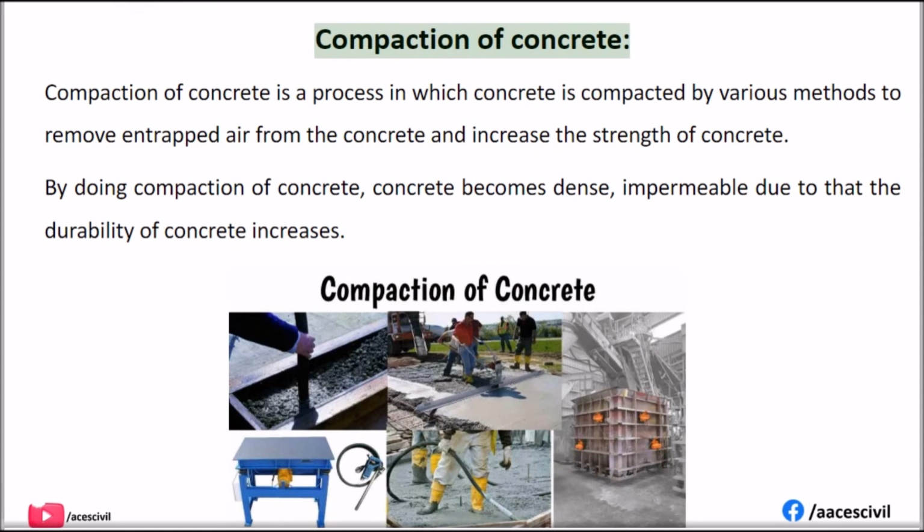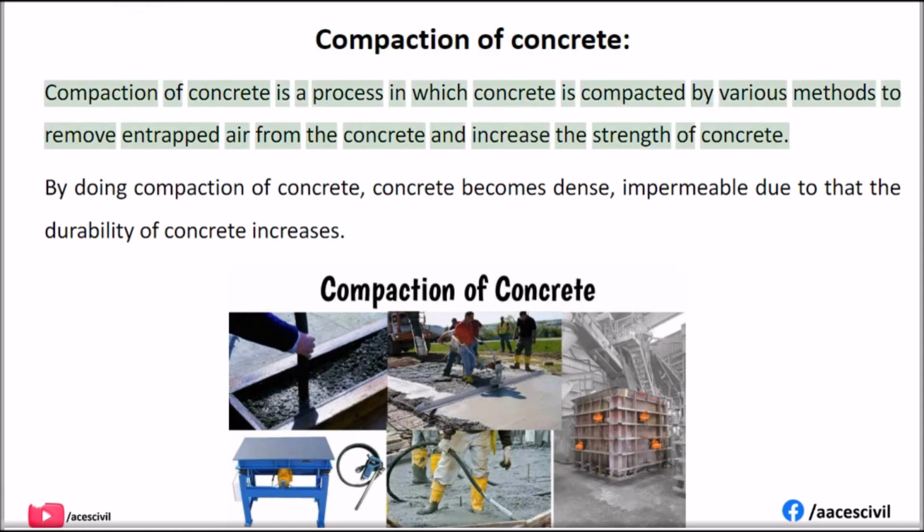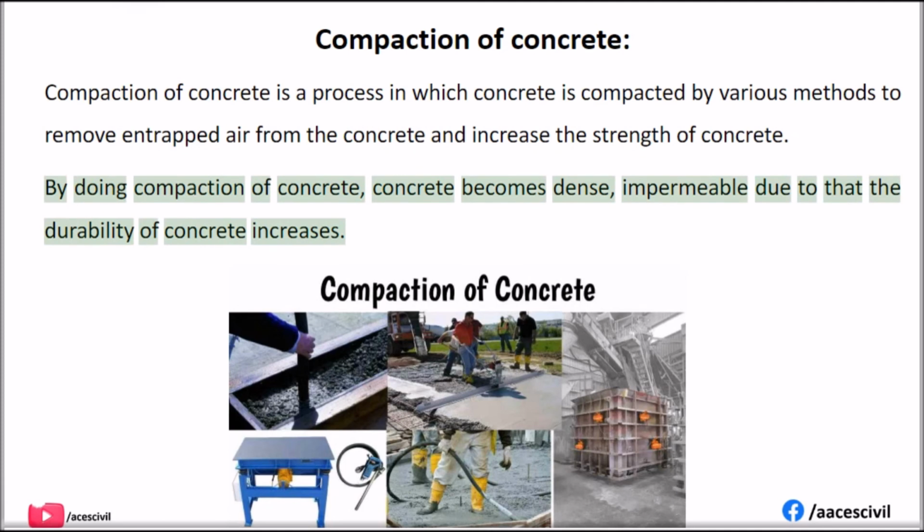Compaction of concrete. Compaction of concrete is a process in which concrete is compacted by various methods to remove entrapped air from the concrete and increase the strength of concrete. By doing compaction, concrete becomes dense and impermeable, due to which the durability of concrete increases.